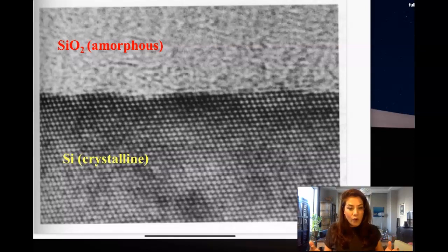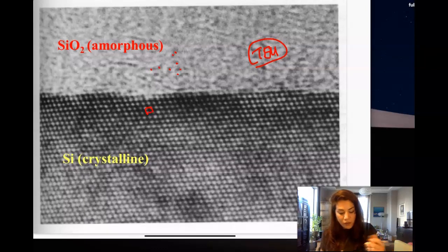We're going to see today in the characterization methods that you can actually observe the atomic stacking, the position of these atoms in the material, with a tool called a transmission electron microscope. This is a TEM image of an amorphous and a crystalline material. As you can see, these dark points are atom centers. In the crystalline one, there is an order. You can observe a 2 dimensional repeating order of the atoms. You can also detect vacancies or dislocations if you pay more attention to the details here.